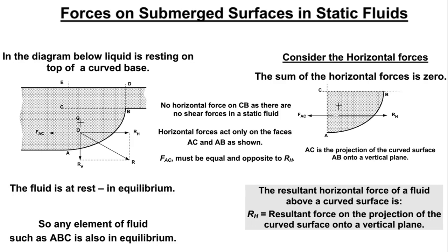Okay, so now in this diagram that we are given here, we've got a force that is acting at this point, which is a curved part. So maybe we've got water in a pipe, then we've reached a point where there is a sudden contraction from a bigger pipe to a smaller pipe. So there's a force that is going to be exerted here. We need to first solve the force in the horizontal direction and also in the vertical direction. Then that's when we can find the resulting force.